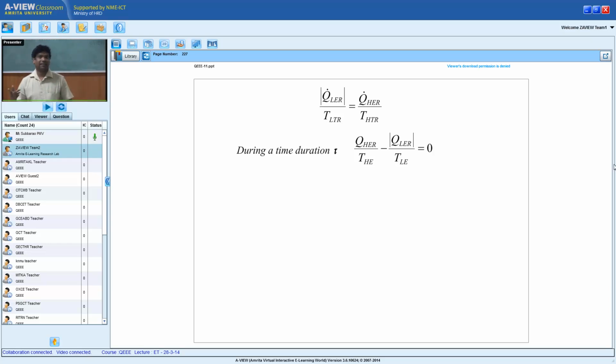So that was the great idea of Carnot for heat input and heat rejection: unless you achieve it isothermally, you cannot get the best deal. Why? Unless the temperature is constant, how can I say I have achieved the highest? If the temperature varies with time, obviously it goes from minimum to maximum or maximum to minimum. So during this time you haven't achieved the minimum, only some average value. This average value is lower than the higher one and higher than the lower one. So you haven't done the job at all.